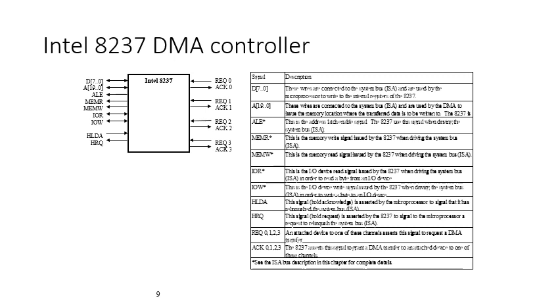So in the previous lecture we talked about DMA, the direct memory access controller, in detail. When a peripheral wants to send data to memory, we can use a DMA controller, so we do not have to initiate any interrupt like we were using with standard IO and memory mapped IO. Rather, we can simply use direct memory access to send data from peripherals to memory.